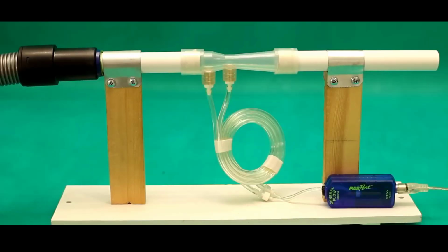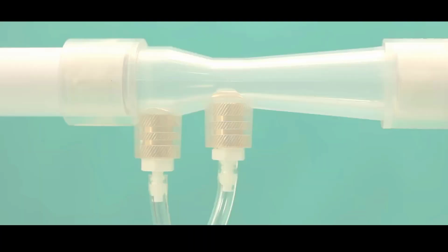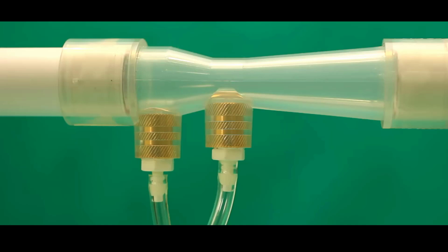This equation allows us to measure the speed and volume consumption of a gas or fluid flowing through the pipe. To do this, a special device is inserted into the pipe. It is called a Venturi tube by the name of its inventor. A differential pressure sensor is attached to the tube. It measures the difference of pressure between the narrow and the wide sections of the pipe. The speed of flow calculation is based on this difference.